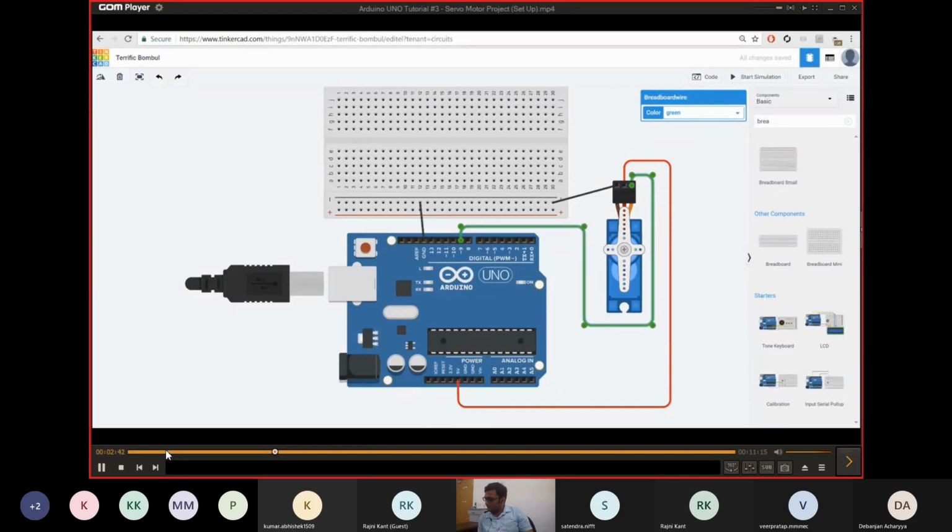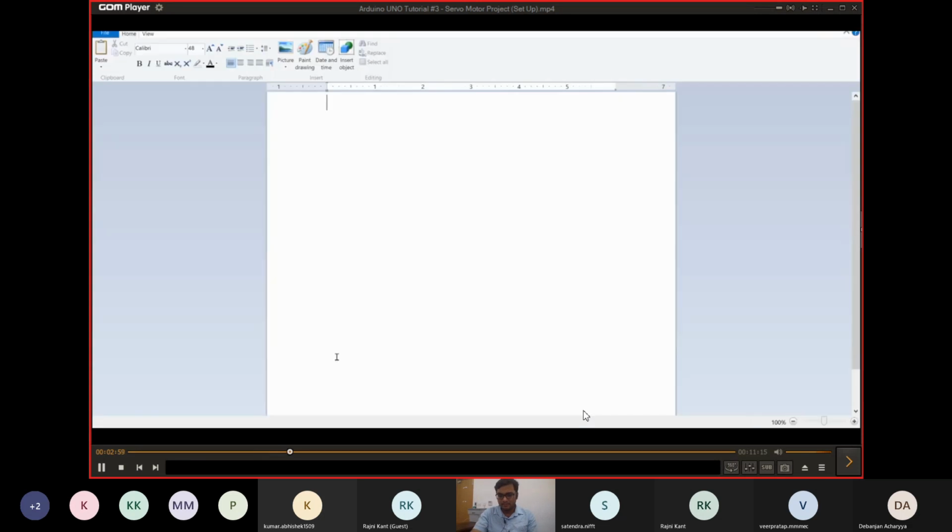The servo runs in a very specific and special way. These are all digital ports over here, so everything really between 0 and 13 is considered a digital port. Now we will stay away from 0 and 1 for specific reasons which I'll get into later, but all of these are digital, which means digital ports can have either a 0 or a 1 signal. That means it'll either send a 0 or a 1, or it will receive a 0 or a 1.